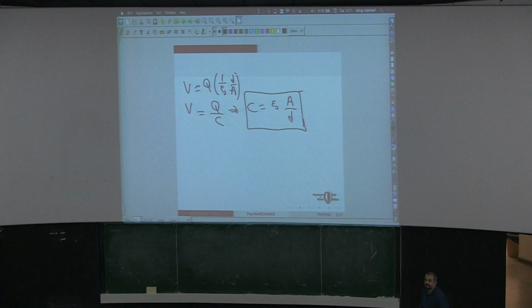Now, every material has a limiting value of an electric field that it can resist. If the electric field is much higher than that critical value, then current will start to flow through it, because you are basically breaking the bonds between the atoms and the electrons. You are breaking off the electrons, which then start to move. But if you want to store some charge, separate the charges, you have to make sure that the electric field that you are creating is lower than that breakdown limit. That is, your potential difference is lower than a given limit.